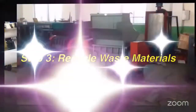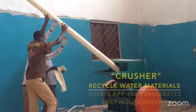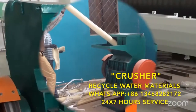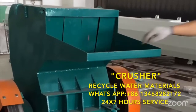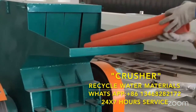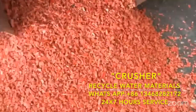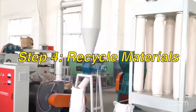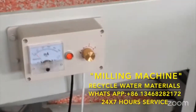After that, labeling, then recycling waste. Last, the fourth step. Suppose the pipe is not good initial material, you have to cut it and add that pipe in a crusher. Again, this granule, 20% or 10%, you can add with the virgin material.